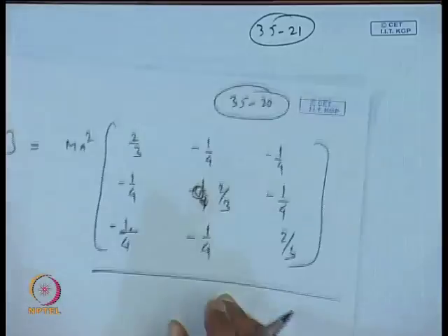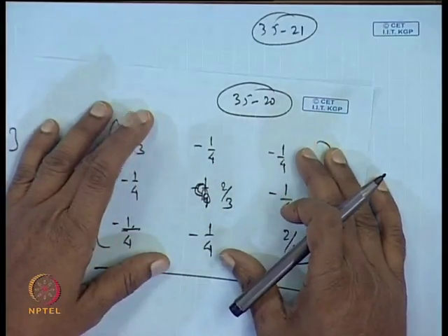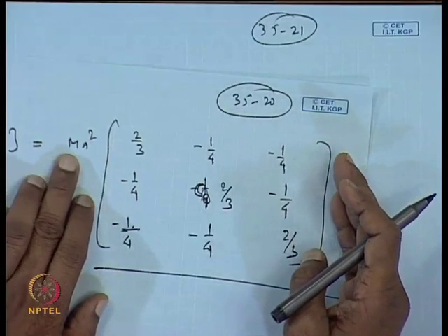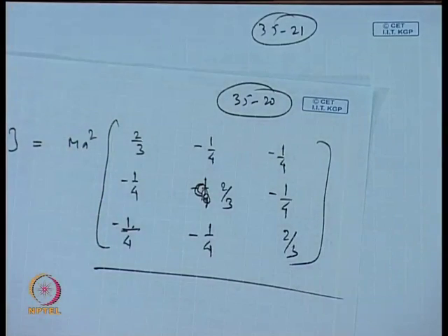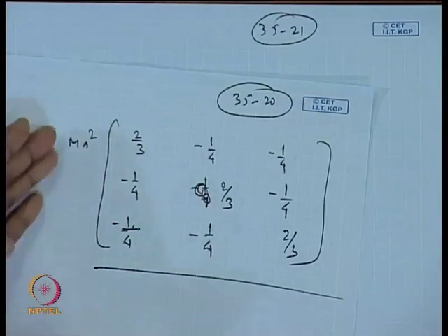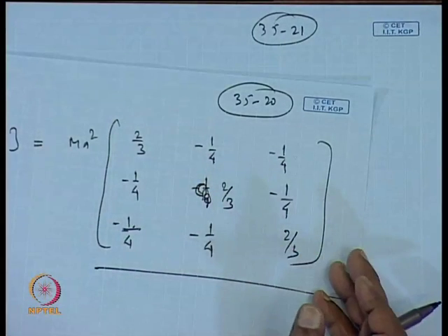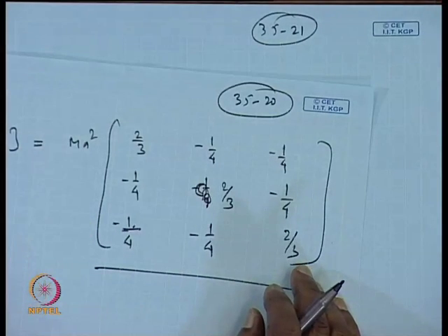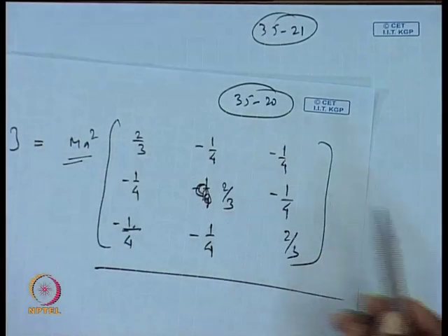So, for solving for the eigenvalues, what can we do? We can work only with this matrix here, which has the numerical values, and whatever eigenvalues result, we multiply by m a square to obtain the required result. Or either we can keep it inside, then subtract the corresponding lambda in the diagonal terms and solve for the determinant. And there you get the eigenvalues, where the m a square term will appear directly.